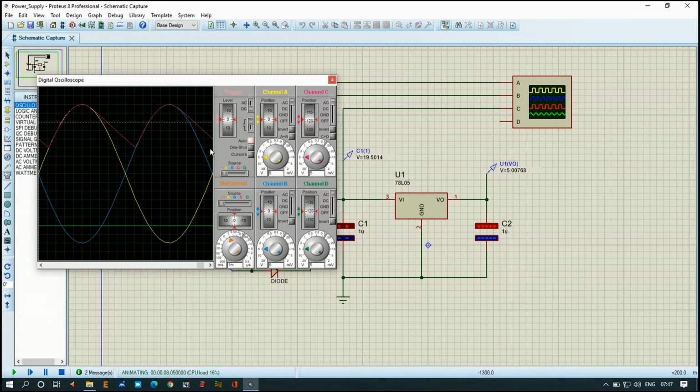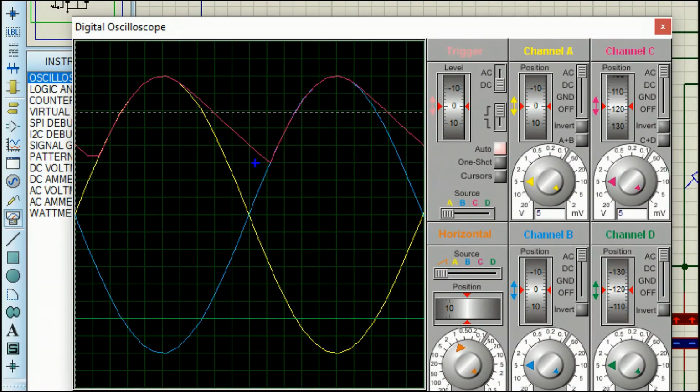It is varying from this point. So this is 19 voltage. This is 0 voltage. This is 19 voltage. And this is peak 40 voltage. So it is going from 19 to 40 and again gradually comes back to 19, and again it goes to 40 and goes back to 19 again. So this variation is too high here, so filtering is less.